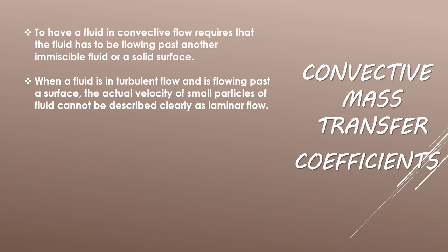Although there is one particular problem wherein, in the case of agar, we have dipped it into a turbulent pure water solvent. In that case, though we have molecular diffusion, we had assumed that the small particles are behaving as if in laminar flow. Now, in real convective mass transfer, these small particles that are diffusing past another immiscible phase, or that are coming from a solid surface to a non-diffusing flowing fluid, are actually not in laminar flow. They are in turbulent flow.